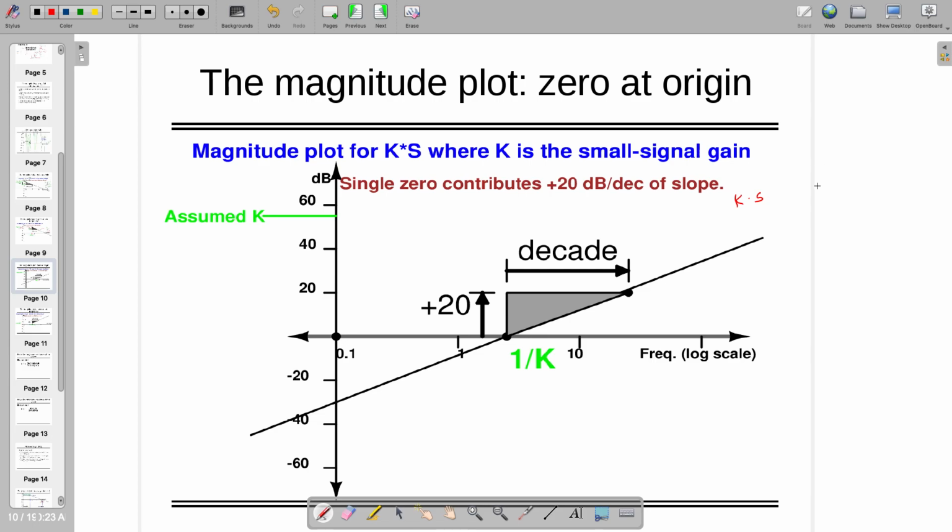So what you have to do, you have to go to the frequency of 1 by k. If you have the transfer function which looks like this one, then it's equal to 20 log k plus 20 log omega. Do you agree with me? When I'm writing this, I want to find out what is happening at the 0 dB value.